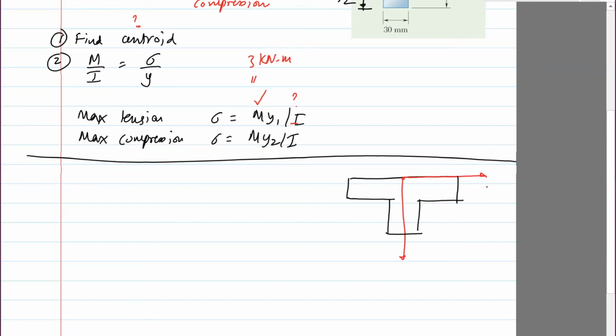So let's say that this is Y, this is X, this is my 0, 0, and that's arbitrary. I just chose it to be that way. You can choose 0, 0 to be anywhere. So what I need to find is the centroid, which is probably somewhere here, is a guess. It's going to be the y coordinate, so C is equal to summation of A times y divided by summation of A. So when I say summation of AY, I'm going to break this down into two sections.